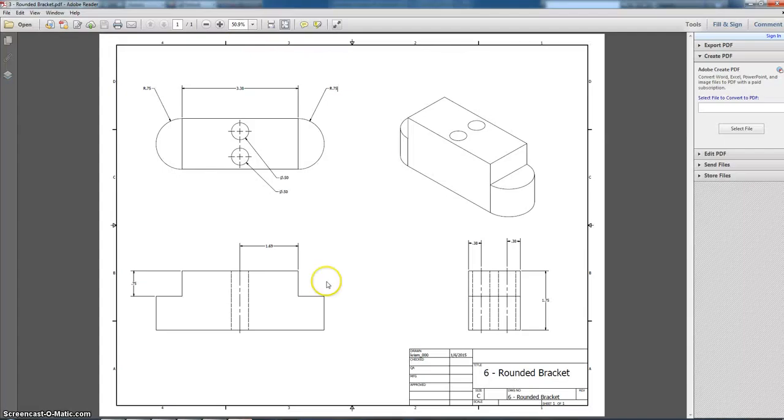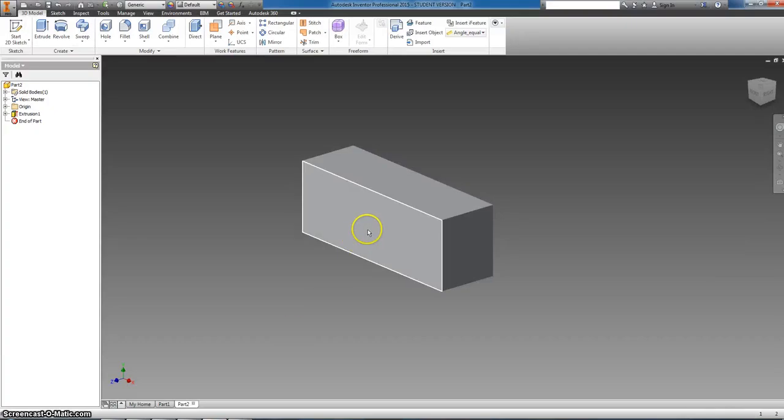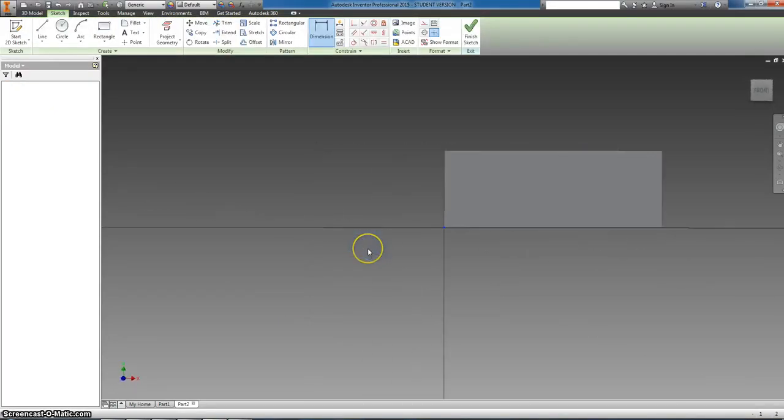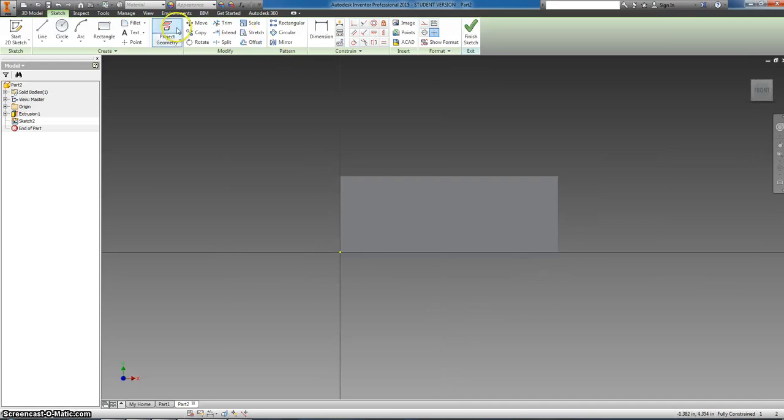So we do have a choice now. We can choose to do the two holes on the top or start chipping away here at the sides. I think I'm going to start here. I'm going to draw on this side, and I'm simply going to take the rectangle tool and create a rectangle here, and I'm going to create a rectangle here. Using the dimension tool, I can tell the program that these two squares that we are chopping off need to be 0.75 each way. So essentially it is a square.